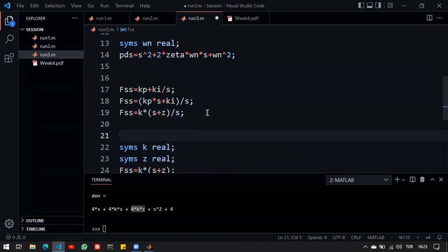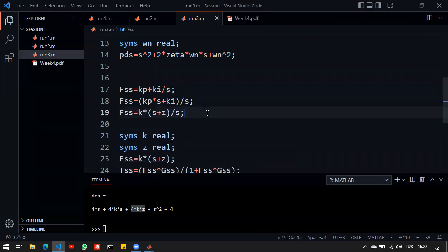Now, in terms of the root locus, I can see that I'm adding an s term, so I'm adding a pole here at the origin, and I'm adding a zero. So designing a PI controller corresponds to adding a zero and a pole at the origin, but the location of the zero needs to be determined. And then once I've done that, I'm choosing a P-type controller.